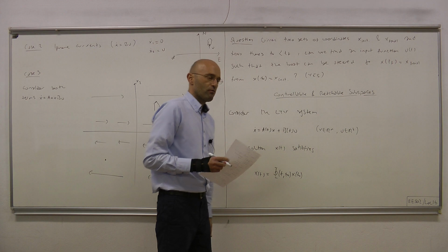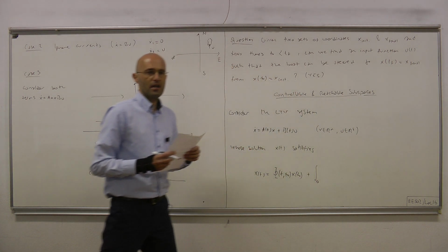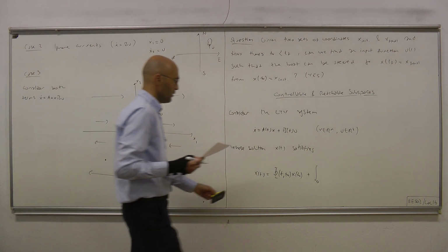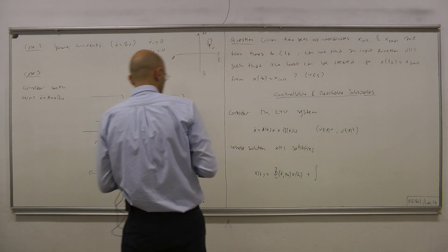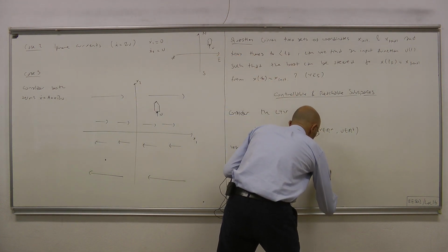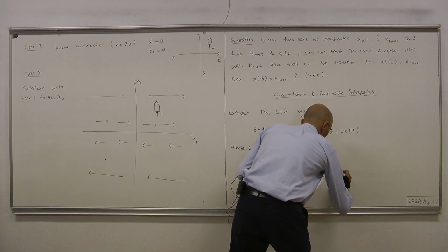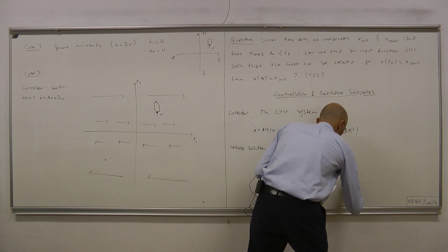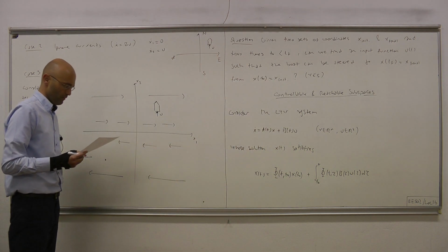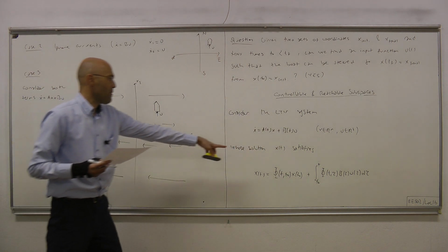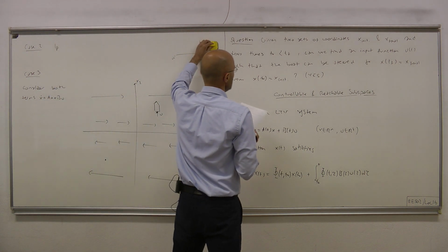That's the homogeneous part of our general solution. If you have non-zero input, then you also have the effect due to the input, which is evaluated through this integral, from t0 to t, of phi(t, tau) B(tau) u(tau) d tau. Having remembered this solution, we're ready to introduce these two subspaces.